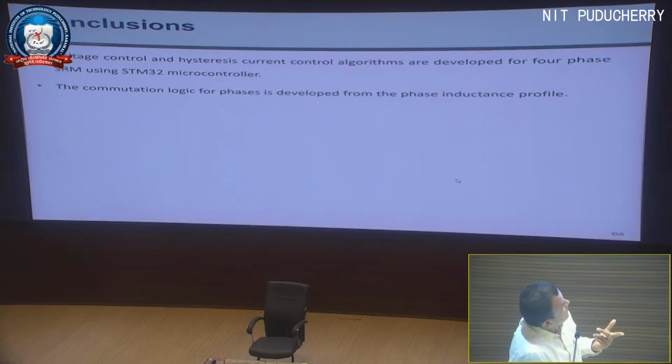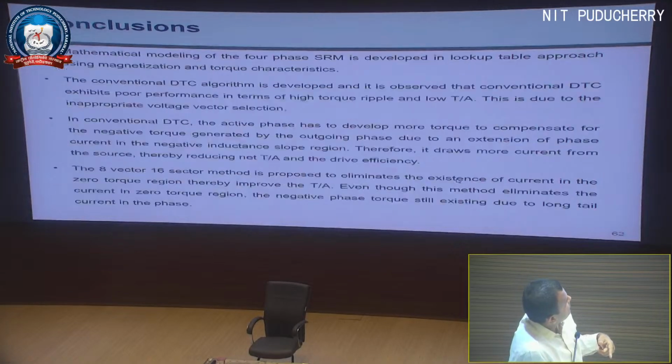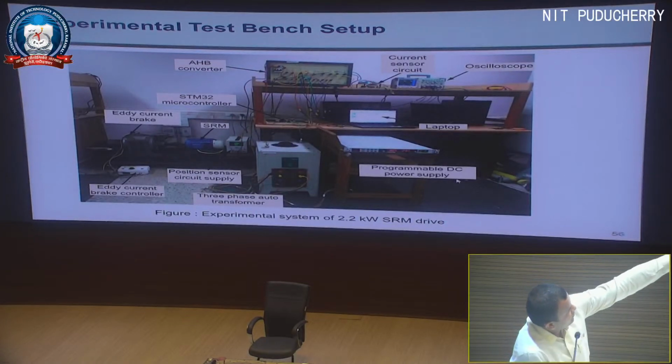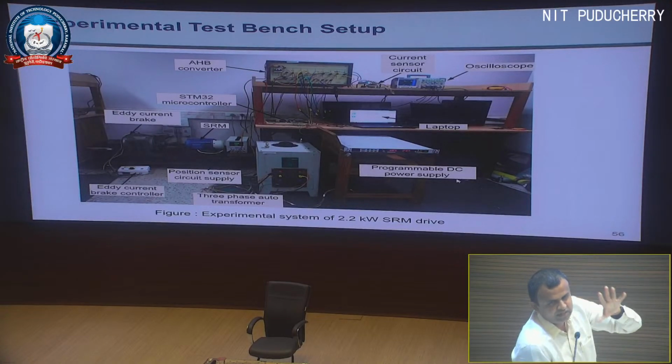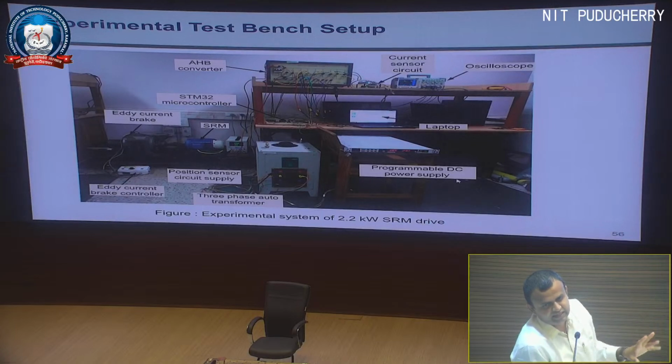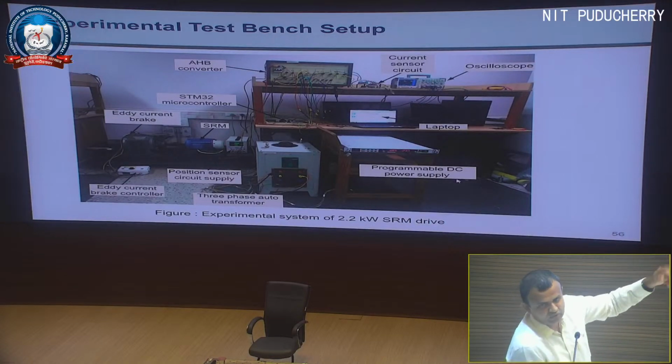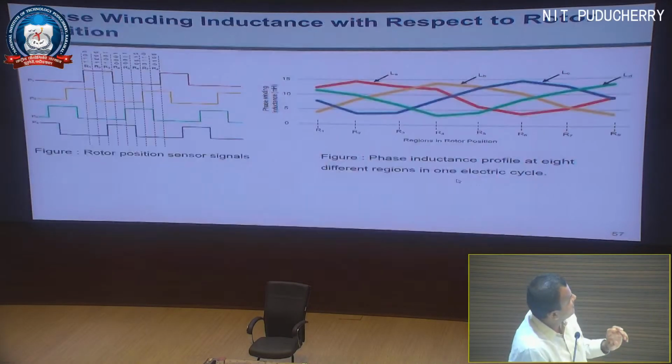And then we use an STM microcontroller for the control purpose, which is shown here next to the laptop. So we have an STM32 microcontroller. The beauty of that is that sir was also telling about the Raspberry Pi Pico, but there is a limitation, right? The frequency and the number of channels. So actually the scholar went for a 1-week course and then he studied. And the beauty is that we can also interface MATLAB with that one, and then generate the pulses to that asymmetric H-bridge converter.